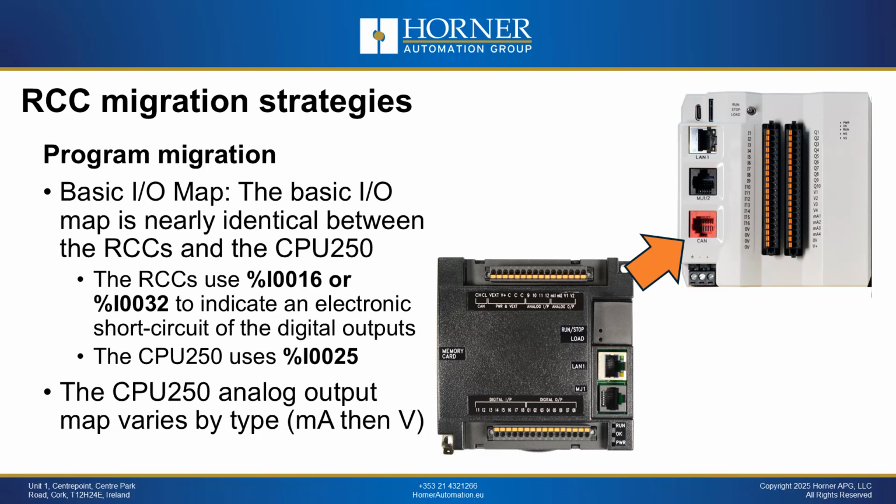There is a feature that a lot of customers do not always take advantage of, and that is a digital input register, %I bit, that will turn on if you have a short circuit on one of your digital outputs. That is available with every OCS model that is out there. A lot of people do not take advantage of it.